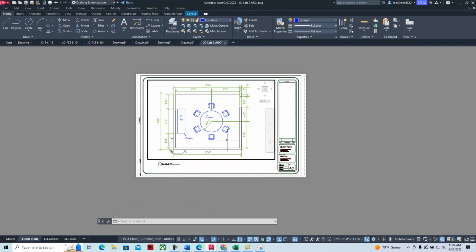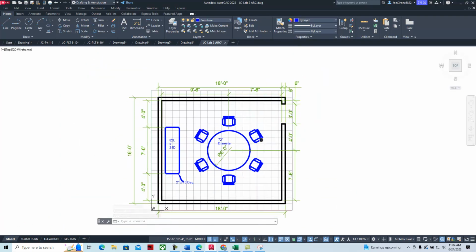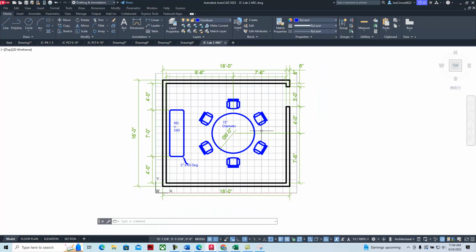And so this way, if somebody took a printed drawing down to the facilities department and they wanted to see if the drawing would fit into the room, they can go through and measure the size of the door opening and things like that, because the idea is that we create the drawings in full size in model space. And so this is actually 16 feet real life units, and it'll give us that feedback right here in our CAD system. It says 16 feet there.